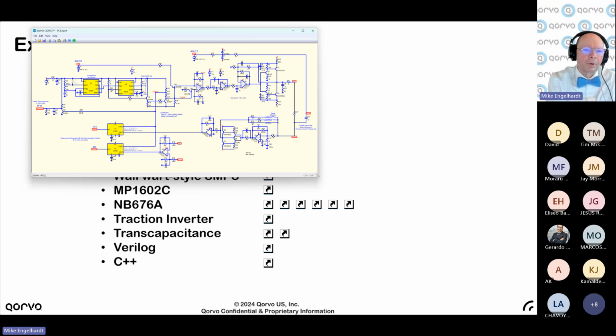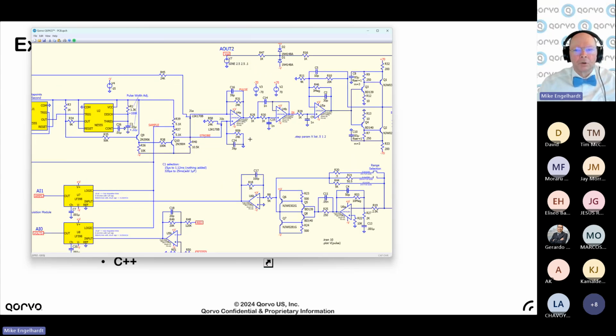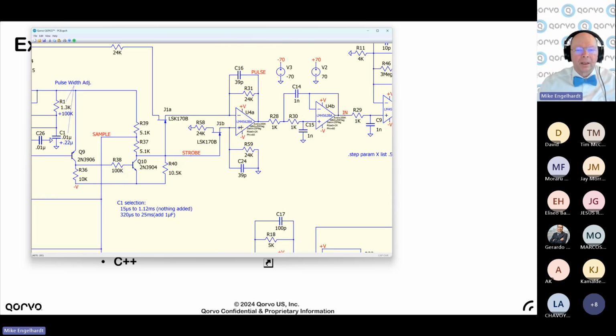And so you have to put your own time base and sample-and-holds for the signal for the converter. Well, so this is the circuit I use. Here are the sample-and-holds. Off the shelf worked fine for those. And to convert a DC level into a precision pulse, the normal way of doing that is a JFET and an op amp.